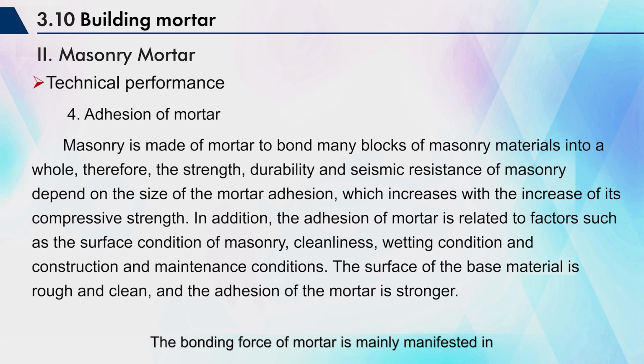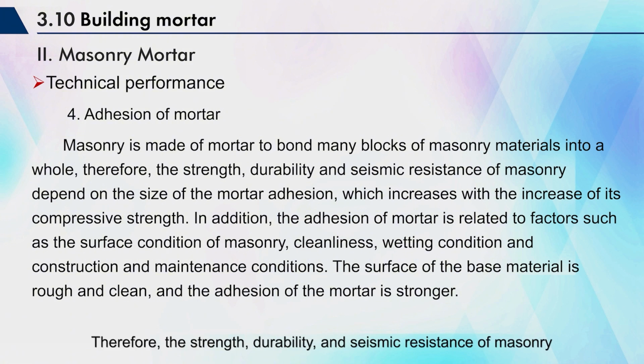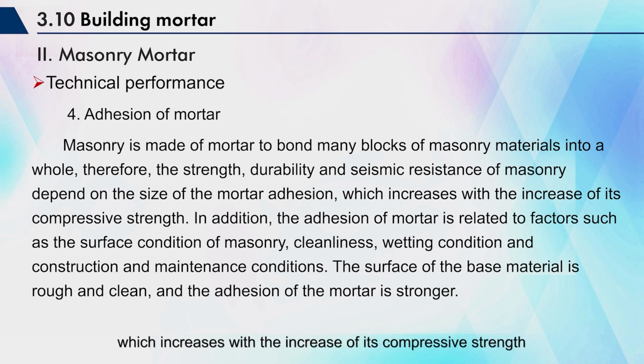The bonding force of mortar is mainly manifested in masonry, which uses mortar to bond many block-like masonry materials into a whole. Therefore, the strength, durability, and seismic resistance of masonry depend on the size of the mortar bonding force, which increases with the increase of its compressive strength.